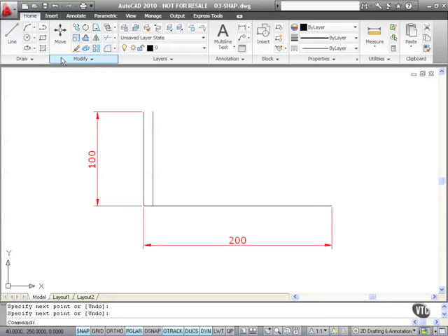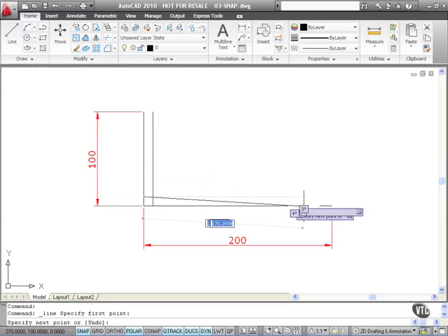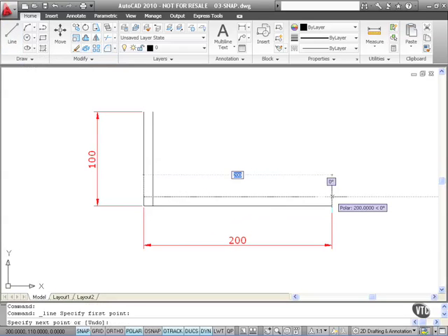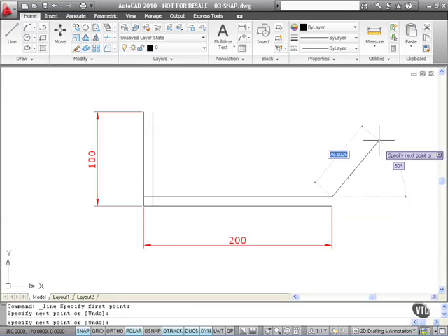So I might want to do a horizontal line now. If I go for this increment just here and get the crosshair here and drag this way and line it in with this line here using the snap and then Enter to finish, I now have an exact intersection 10 upwards and 10 across from the original corner, the original intersection of the two lines. So as you can see there, Snap is extremely useful.